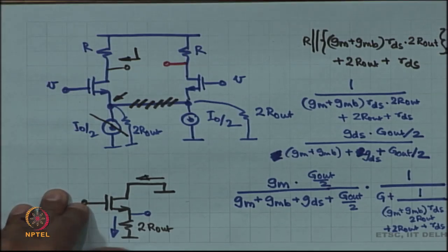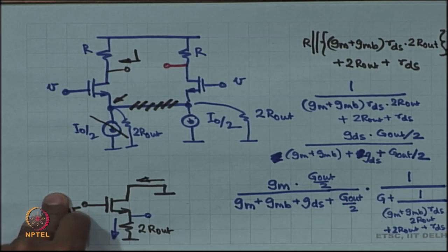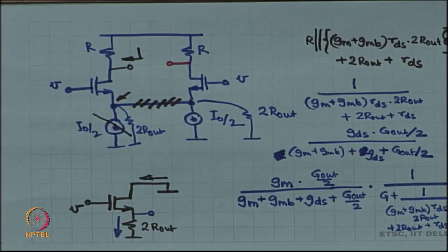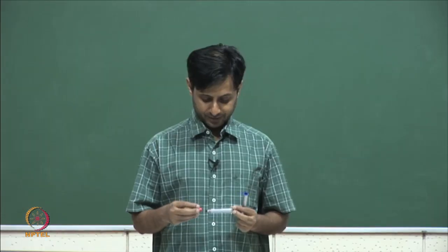All right. So, in theory there is no point in trying to measure this, it is equal to 0, we know beforehand. In the lab, however, this is what is straight away interfering in your signal. This is the interference that went into your signal and is becoming part of it. Okay. So, this is not a very nice thing, it is not very nice to have common mode leaking into the differential mode.